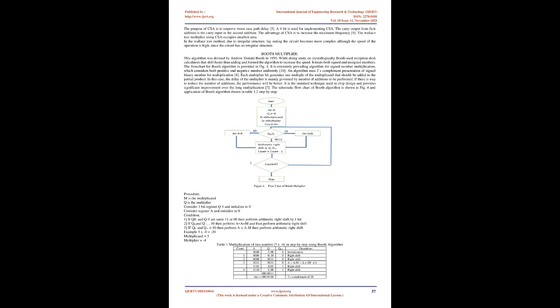Speed, area, and the power consumption of the multiplier will directly be proportional to the efficiency of the compressor. The 3:2 compressor is used to make the overall multiplier faster. In a Wallace tree using a 3:2 compressor, 3 partial products are passed to a 1-bit full adder, which is called a 3-input Wallace tree circuit, and the output signal is applied to the next stage full adder of the same number of bits located at 1 bit higher position.